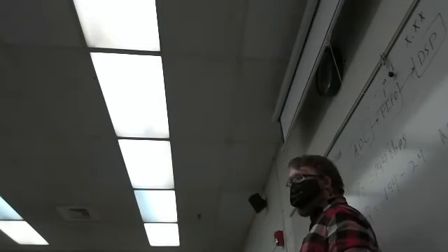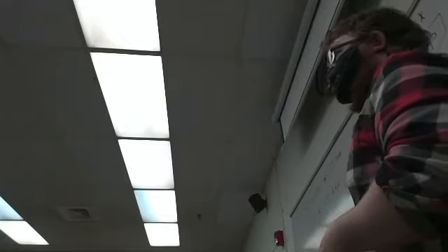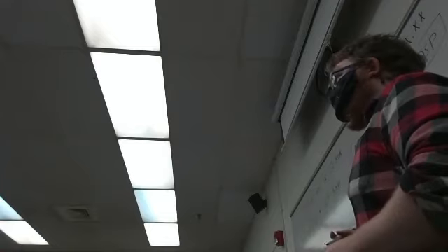So my FIFO depth is 12, so it's capturing a whole sample at a time, and then it's pulling it in and doing something with it, right? So now we have to figure out, if I'm filling my FIFO at 144, I'm emptying it at 24. How long before that fills up? Well, now it's just a time conversion, right? Because this is in units of kilobits per second, which we can convert to kilobits over second. And now we can start seeing our units. We just realize that we need to get rid of kilobits and get seconds on top, and that's time.